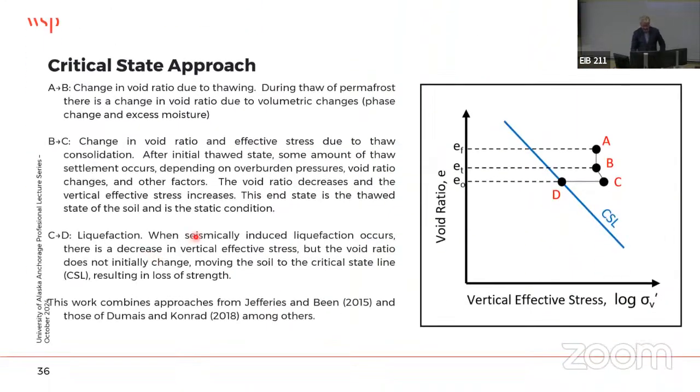All right, and then I wouldn't be doing anybody any favors if I didn't bring up the critical state approach. Any critical state soil mechanics folks out there? Nobody, all right? They don't teach this in school, and this is a tragedy, but critical state soil mechanics basically describes liquefaction really well. And again, we saw a plot similar to this where we have loose soils on this side, dense soils on this side.